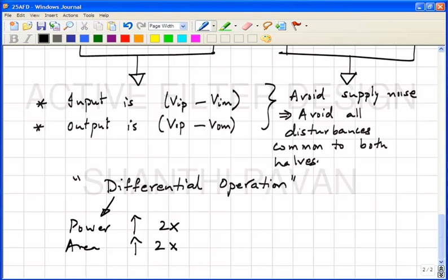What has happened to the dynamic range? Why? What has happened to the peak signal strength? It has doubled. Why? Earlier the amplitude on each side, each arm, was A, so the signal power was proportional to A square.